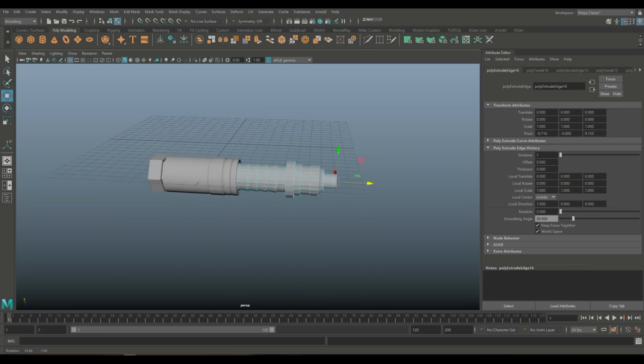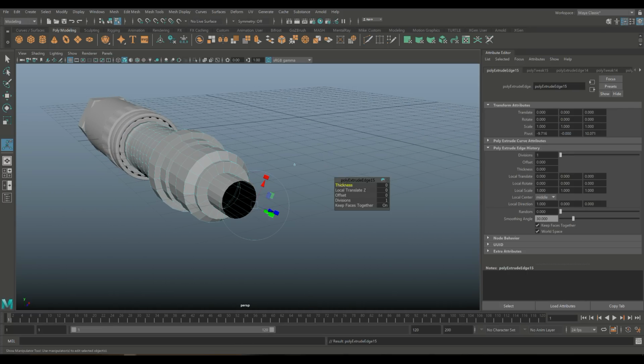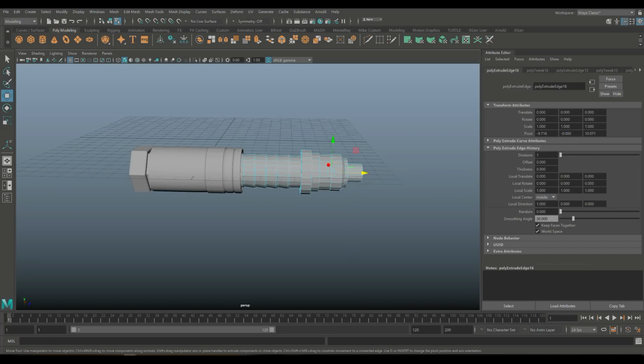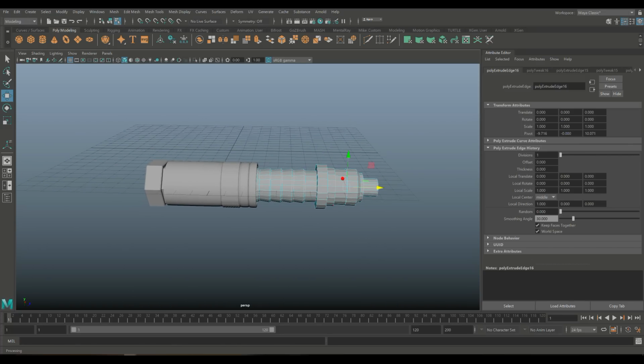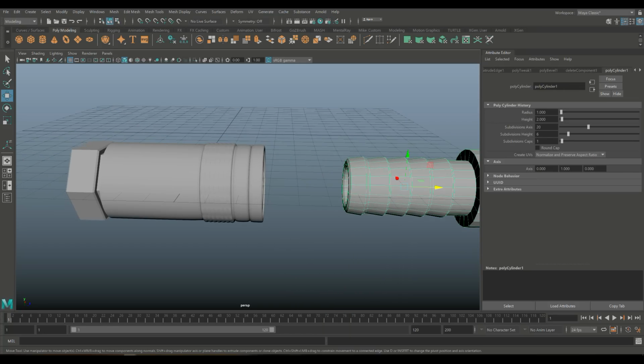Let's look at the overall length. Pretty good. We're going to Control E one more time, R to scale in, G to repeat, and W to push in. Now, probably we're not going to need all of this because we're going to have a hose on it, but I'm happy with that, right? So I'm going to hit W, we're going to pull this out here.